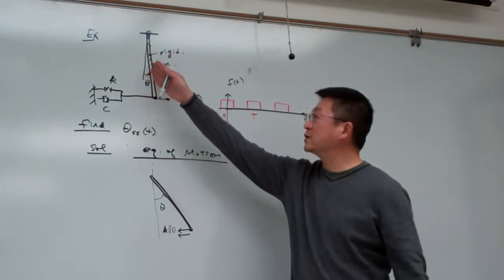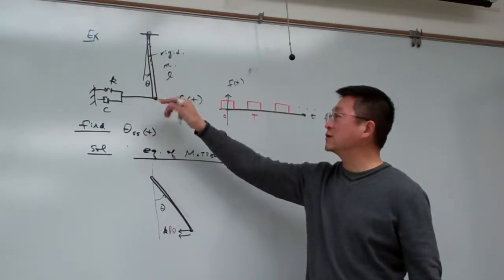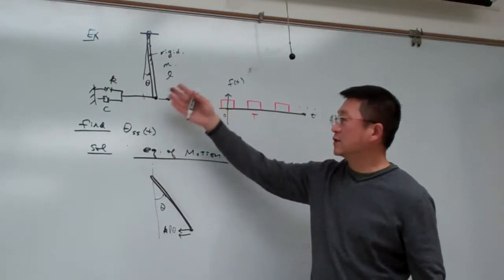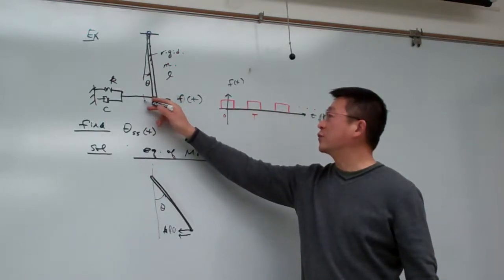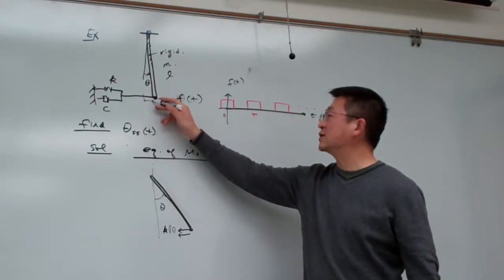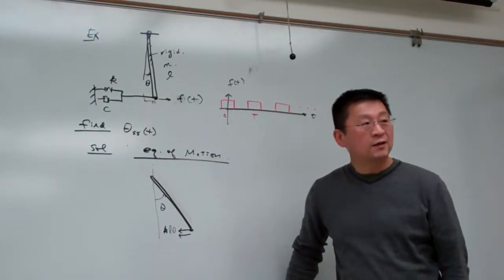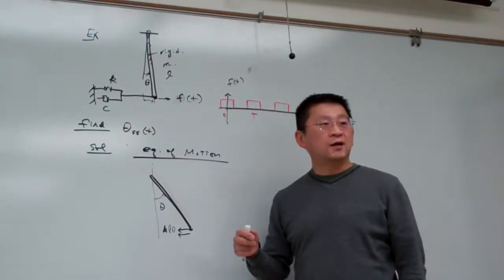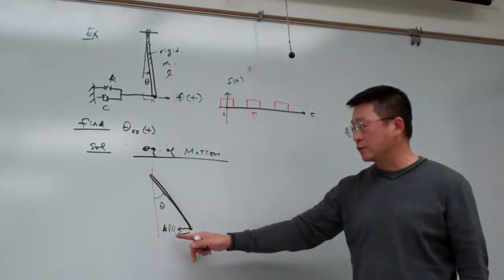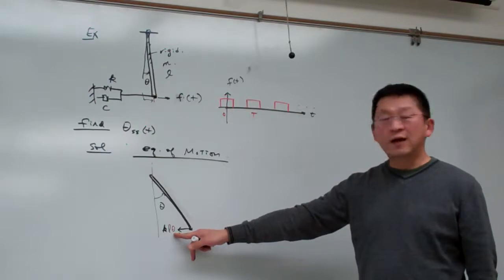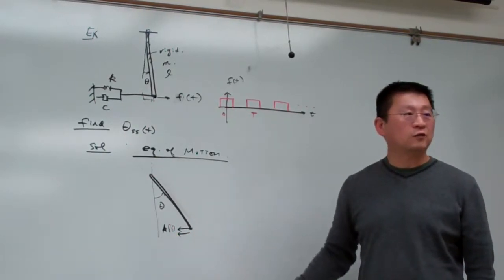Assuming the equilibrium is the vertical configuration, if we swing to the right a little bit, you can approximate this distance as L theta, or L sine theta. But L sine theta is basically L theta when theta is very small. That's the reason we assume small oscillation. Otherwise, we have to deal with nonlinear vibration, which is not the topic here.